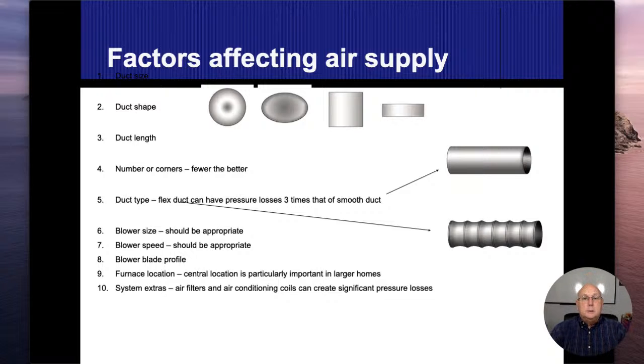Airflow and ductwork. This is another complaint call if you don't take the time to check. You will run into houses that, A, don't even have a heat source in a room. We've run into that a few times. B, they're going to be at very odd locations, like right in the middle of the ceiling someplace, and it was added afterwards. Or you just get a real cruddy flow coming out of it.